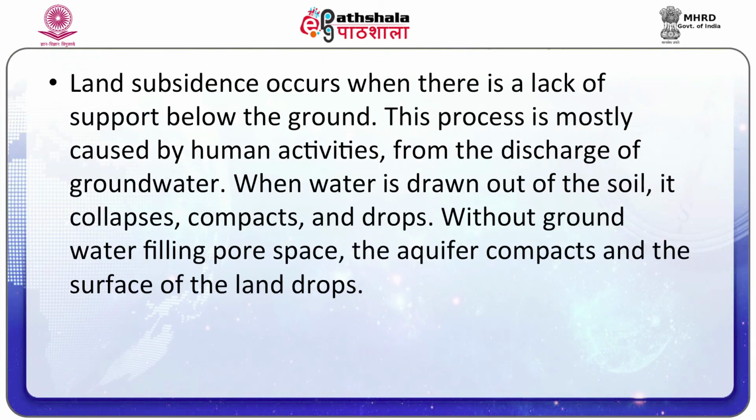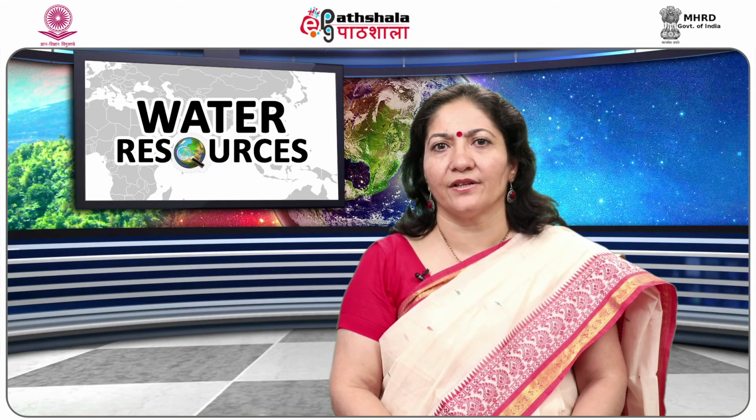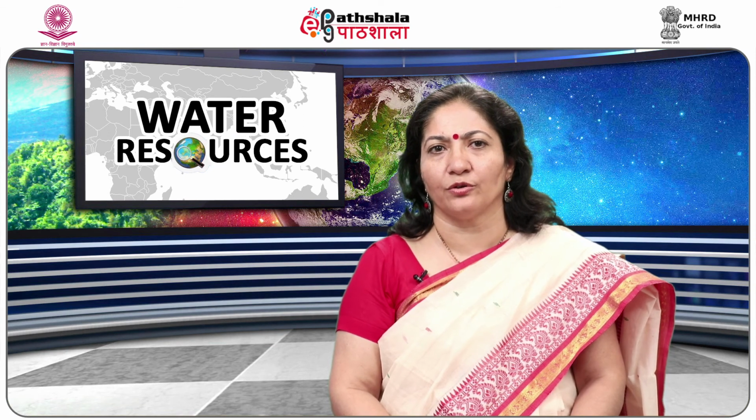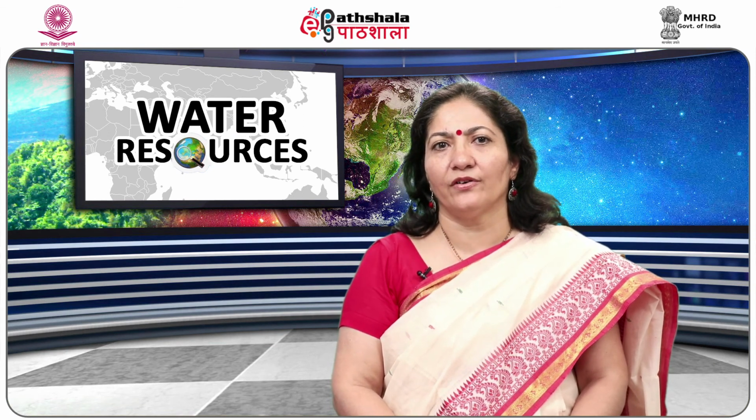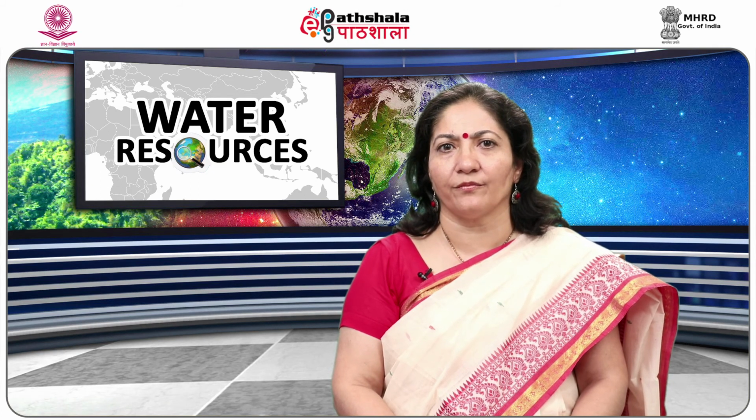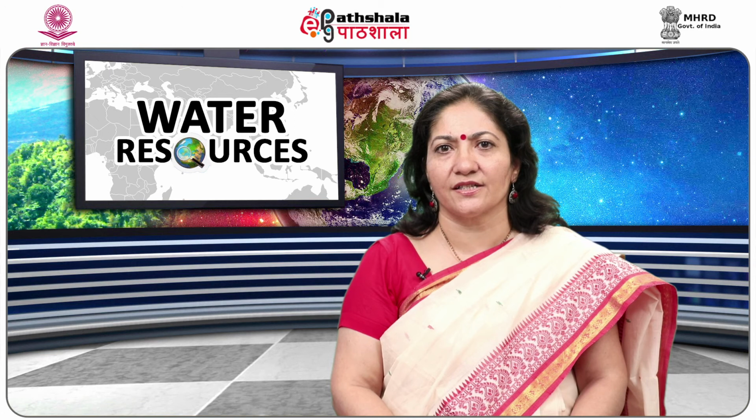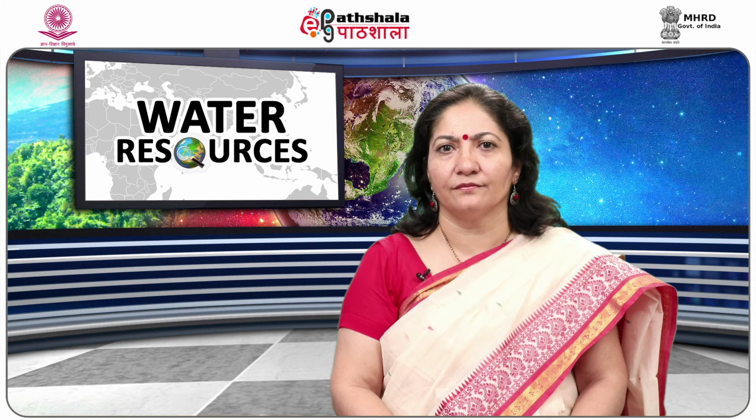Third, land subsidence. Land subsidence occurs when there is a lack of support below the ground. This process is mostly caused by human activities from the discharge of groundwater. When water is drawn out of the soil, it collapses, compacts and drops. Without groundwater filling pore space, the aquifer compacts and the surface of the land drops. This subsidence of land depends on factors such as type of soil and rock below the surface. At times, aquifers are recharged artificially to prevent them from compacting. This recharging is done by pumping natural flood waters and treated wastewater back into the ground.